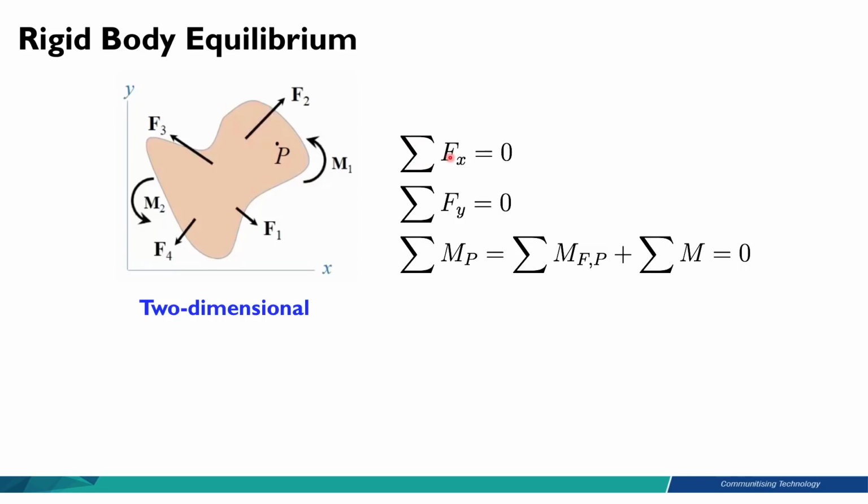So the summation of forces is now equal to the mass of the rigid body multiplied by its acceleration in the x-axis and also the y-axis. And if the rigid body is undergoing rotation, then we have the summation of moments that is equal to Ig times alpha, that we have just discussed in the mass moment of inertia just now.